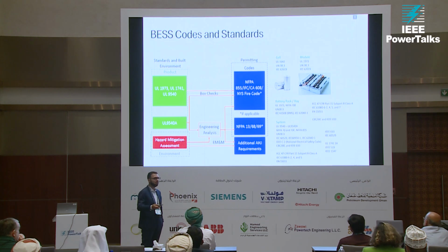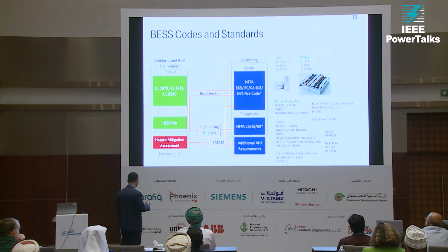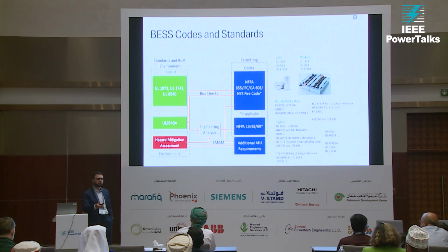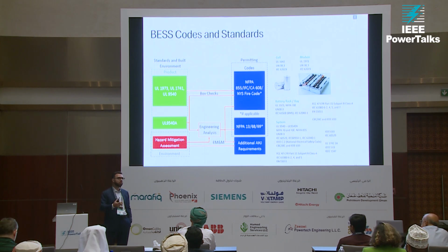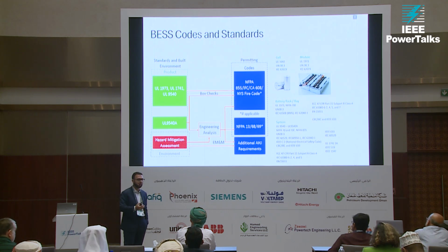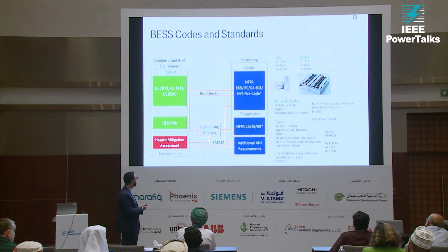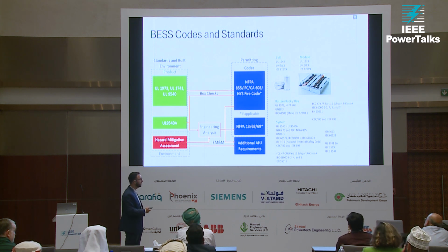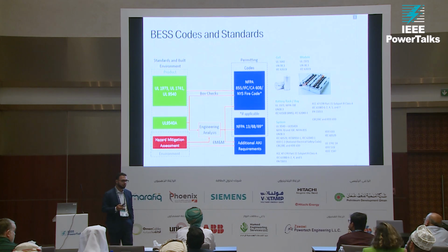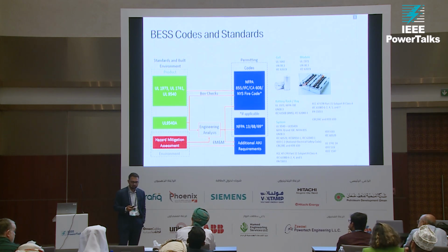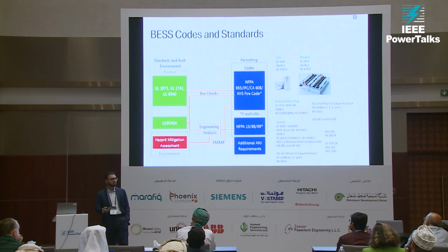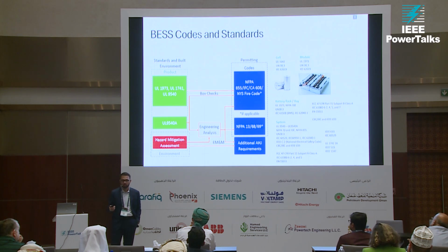NFPA is the National Fire Protection Code. Oman might have its own fire codes. I'm pretty sure they have no provisions for energy storage at this point. So part of the learning is to improve those codes and standards to make sure that the industry is trending toward a safe design and a safe implementation. And just to give you an idea, NFPA 855, I think, got introduced in 2015-ish. So years in when we started implementing systems. So we had systems that did not comply with any of these codes at this point.